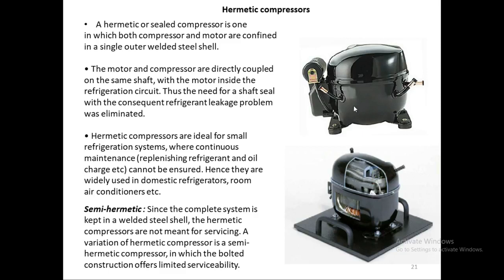So the main reason of making it this way is to avoid the leakage of the refrigerant, because if the motor is separate and the compressor is separate, then there has to be a shaft which is going from motor to the compressor. So you have to seal that shaft. No matter how good sealing you do, after some time it will start leaking. So that can leak your refrigerant also.